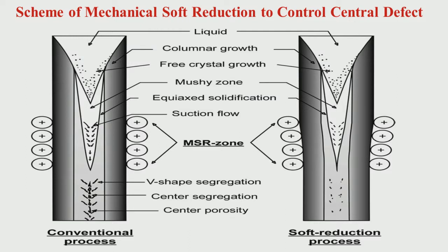Then it comes out of the mold, and if it is a curved mold, you require only unbending or straightening of the strand to make it horizontal. If it is a straight mold, you first require bending and then unbending or straightening to make it horizontal.